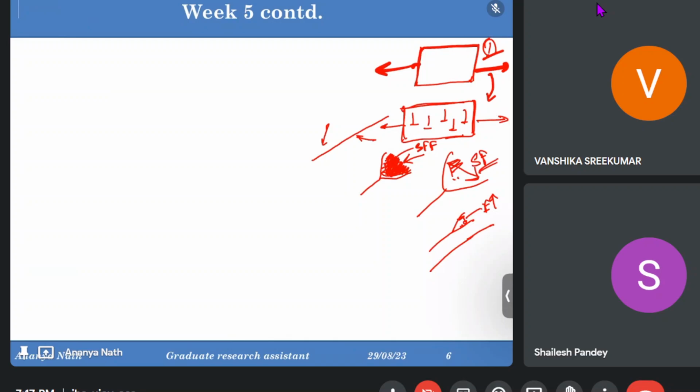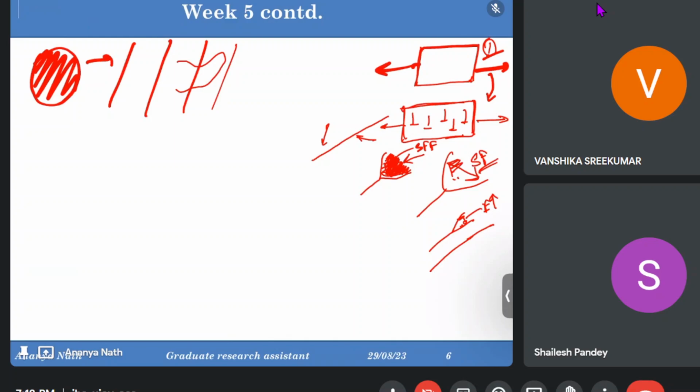So if cross slip is taking place inside a particular plane, and the stacking fault has higher energy, then it will have the tendency to get attached again and restore the original shape and geometry of the dislocations.